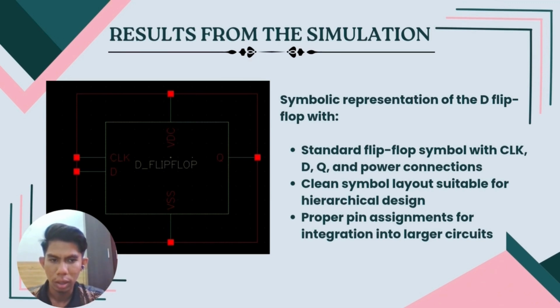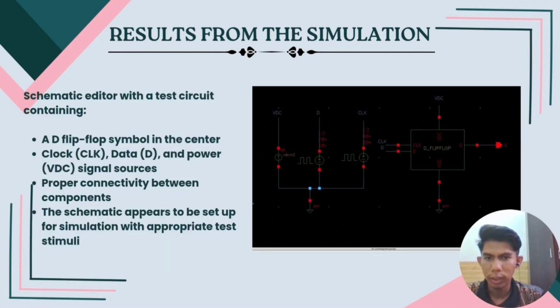This is suitable for the hierarchical design, with proper pin assignments for integration into the larger circuit. This is the test circuit from the schematic editor, which contains the D flip-flop symbol and also contains clock, data, and power VDC as the signal sources.